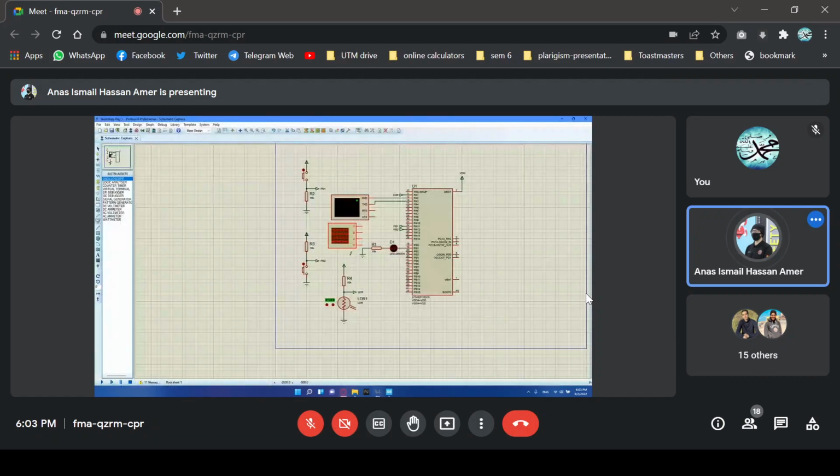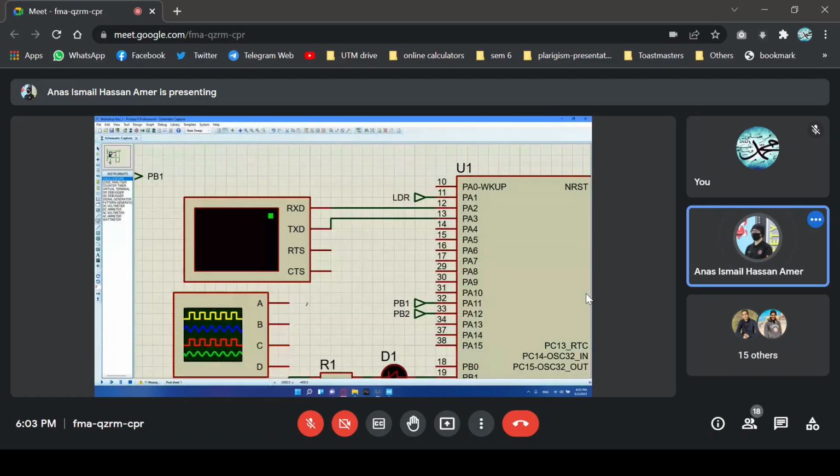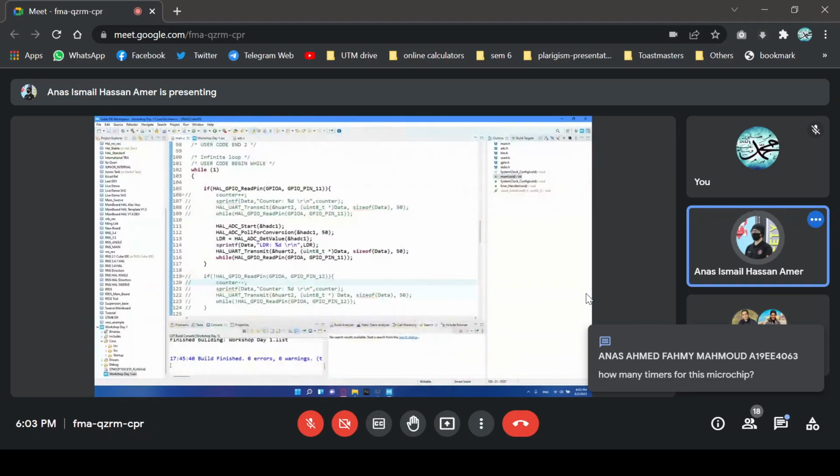If we go back, let's connect A6 to the A port, and that's it. That's all the wiring we need to do to view the waveform of the PWM we're just about to generate.